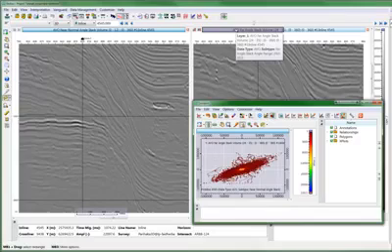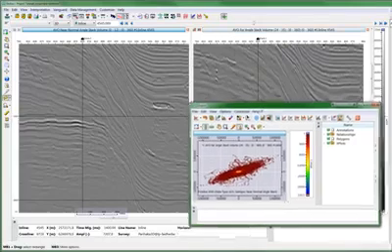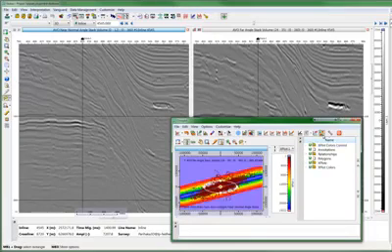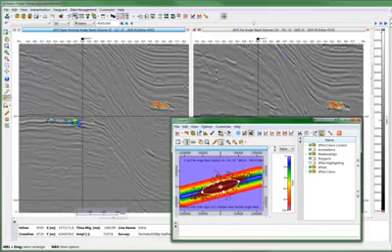By dragging one panel on the other one, we are displaying the crossplot of the near amplitude versus the far amplitude. We graphically compute a regression line on the near versus far crossplot, and we can use this regression line to color the crossplot. By drawing an ellipse, we can exclude points from the coloring, and we can display the points that are colored on the seismic section.